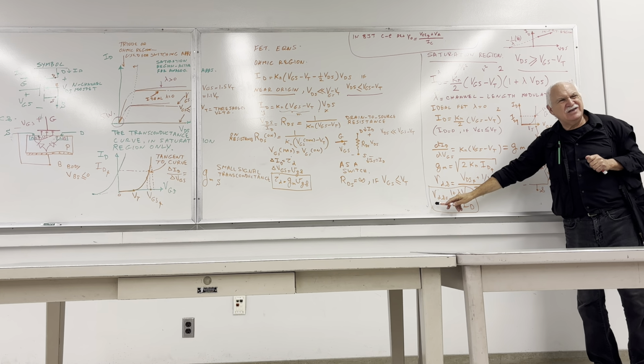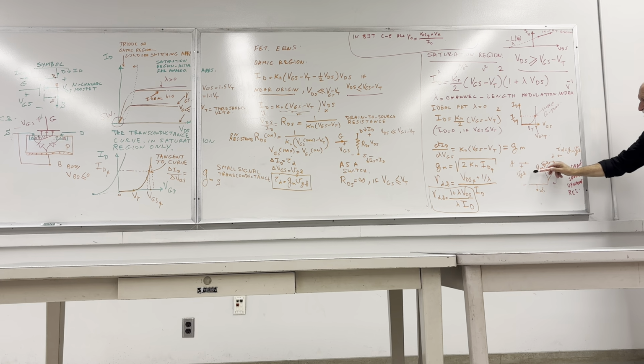You can get an idea about the drain to source dynamic resistance, which should be included here in the small signal model. But we scarcely get to that point. So this will complete both AC and the DC analysis of all MOSFET circuits to come.